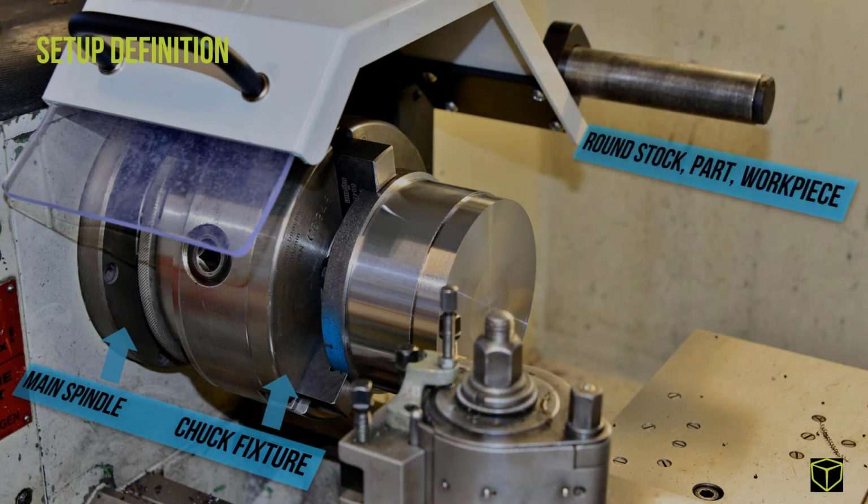To the right of the chuck fixture is the round stock, also known as our part or workpiece. It is critical that the spindle center line be set properly in the software in order for feature recognition to automatically recognize features for machinability.